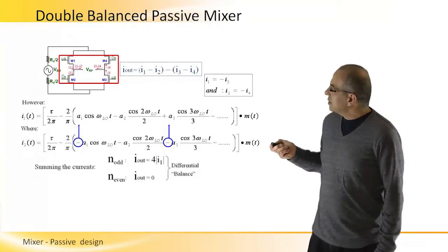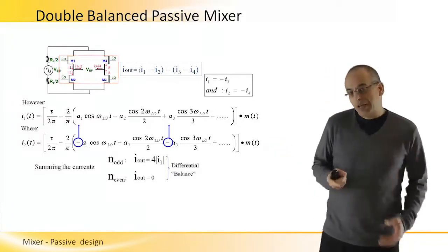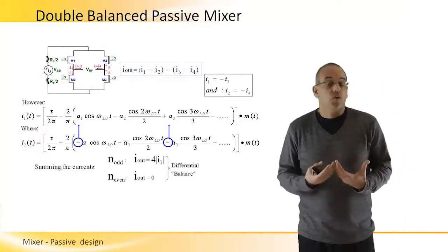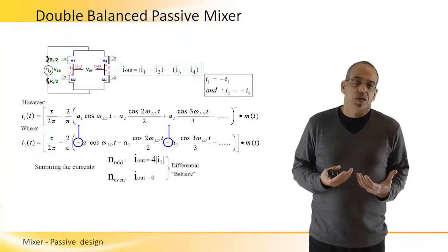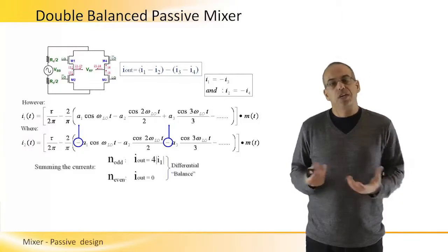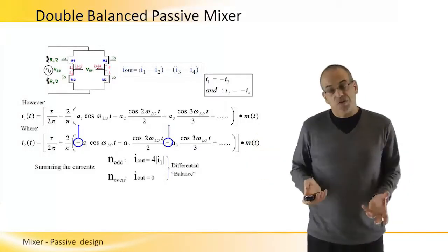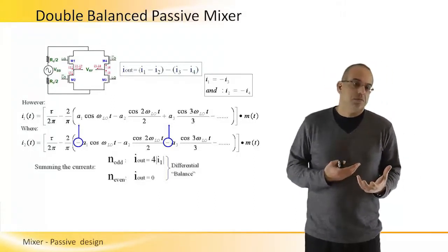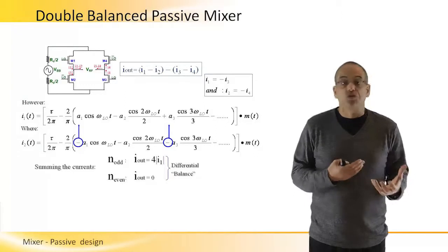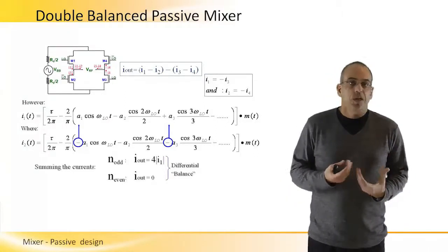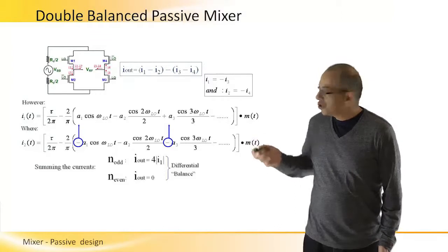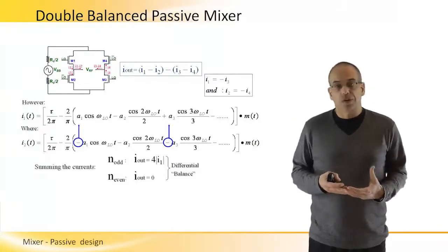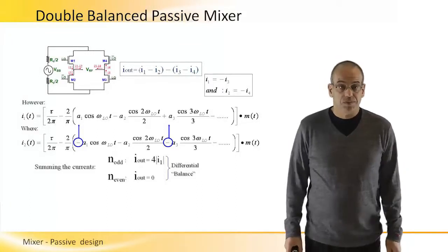So by leaking at opposite phases to the same output, they balance each other, or they cancel, or effectively they reduce the total LO leakage at the output to be very, very low. And when we talk about very, very low, we get figures of close to 30 to maybe 40 dB lower than it used to be with a single switch. So that's the way we improve LO leakage performance.